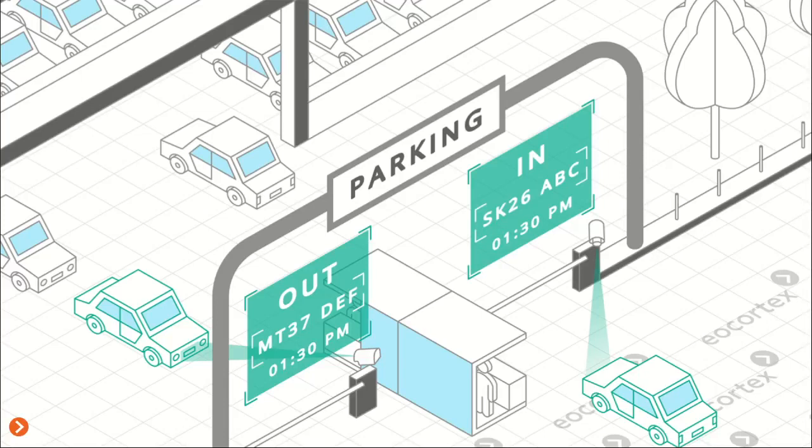Also, it's important to arrange the entrance to the barrier in a proper way. To give the camera a chance to recognize the license plate number, it's necessary to hold it steady. This is performed in the so-called registration zone. In this zone, the vehicle speed needs to be reduced to 20 km per hour or even less. To do so, it's recommended to install a corresponding road sign, a speed bump, or road marking.